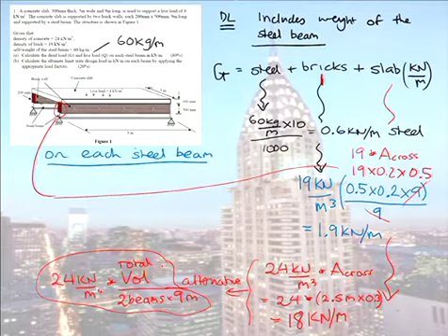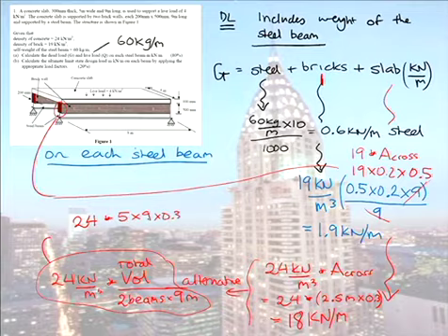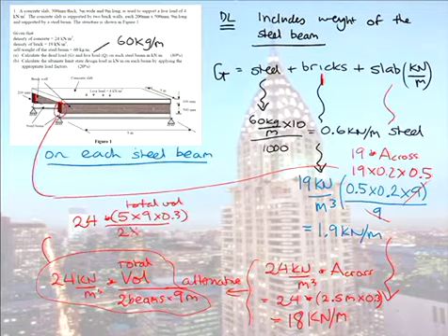And doing it that way, you will get the same answer. So doing it this way, you would get 24 times the volume of our slab is 5 times 9 times 0.3. So that's our total volume. Then we would divide by 2 beams and then 9 metres, and that would also give us a load of 18 kilonewtons per metre.